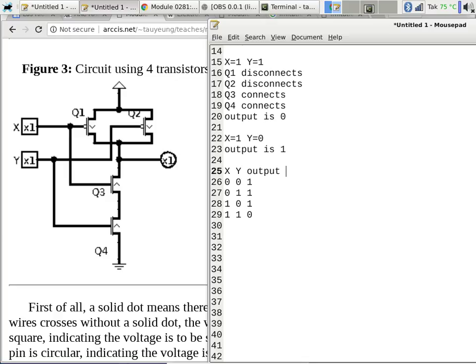It looks also like an AND gate, because with an AND gate, the only one that is different is when both inputs are 1s, and then for everything else, they have the same output. Except this is the flip side of an AND gate. Because if this were AND, we would have 0, 0, 0, and then a 1. This is giving us exactly the opposite of that. We're getting 1, 1, 1, and then a 0.